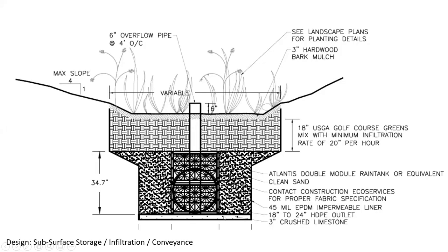And another good example of these types of systems is taking your subsurface drainage. A lot of times they'll use aggregate with a perforated pipe and they'll wrap it with filter fabric. But aggregate only has a 40% storage volume. And so if you take a modular under drain or some other type of arch chamber, whatever it may be, you can actually increase that storage volume. So here's an example. Instead of just using a perforated pipe, we use a tall modular under drain. Each of those boxes can contain 4 cubic feet. So we went from 40% void up to about 90% void.